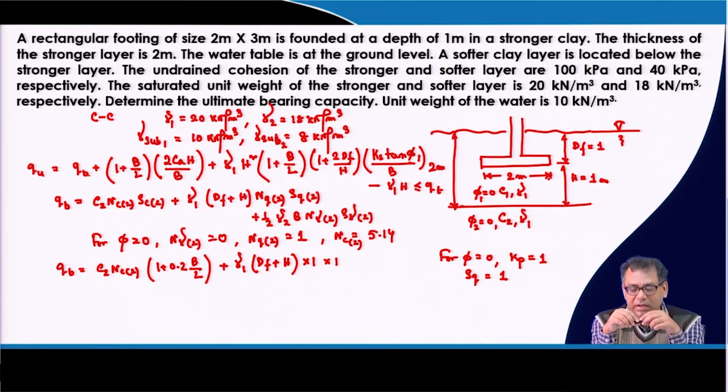But for the inclined footing you can put those recommendations which are given in the original bearing capacity equation by Meyerhof. So, that is why, when I calculate qb, we take the shape factor which is originally proposed by Meyerhof and it is given in the table. So, remember that.